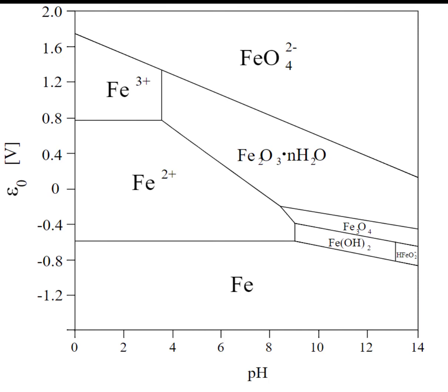We've got a kinetic process going on where the oxide is being fed from the bottom with iron, and it's losing iron into the solution, either as FeO4 2- or as Fe2+, or if we get over close to this line, it's getting lost as iron 3+ into solution. So we're losing our oxide, but if we are in this region, our loss of iron will be slower than if we are in this region here, where it can go straight from the metal into the solution.